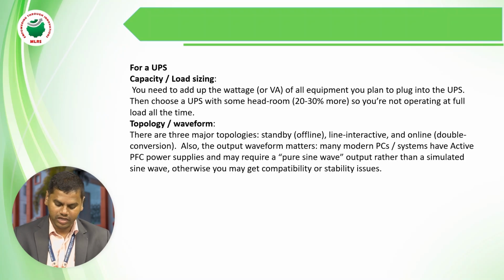The output waveform also matters. Many modern PC systems have active PFC power supplies, and many require a pure sine wave output rather than a simulated sine wave. Otherwise you may get stability issues. So that is the topology or waveform for a UPS, mainly sinusoidal waveforms. That's the main thing here.